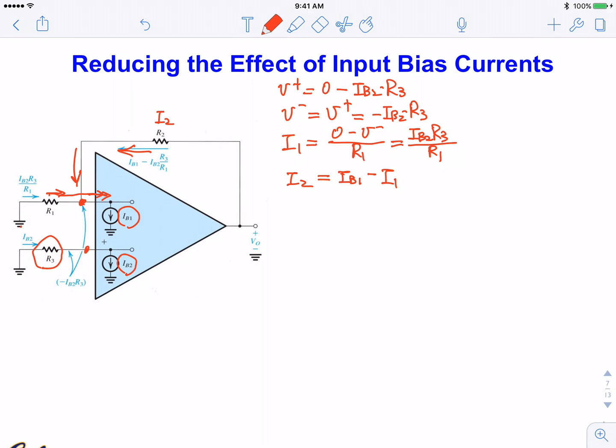And now VO is going to be equal to this voltage here. It's V, this is the V minus terminal, okay? And then plus the voltage drop. You always mark the sign: the current always flows from plus to negative terminal. In the convention, the real sign depends on the polarity of the answer you get. So this is adding I2 times R2, okay?